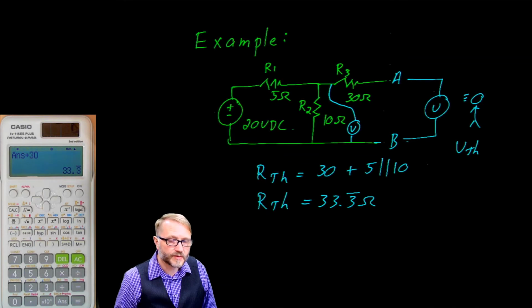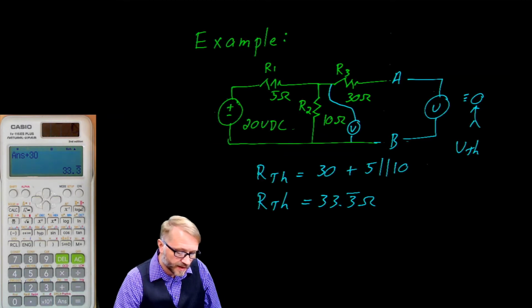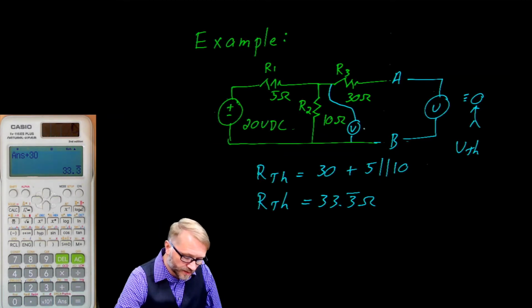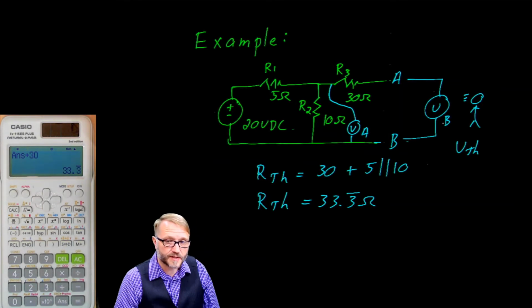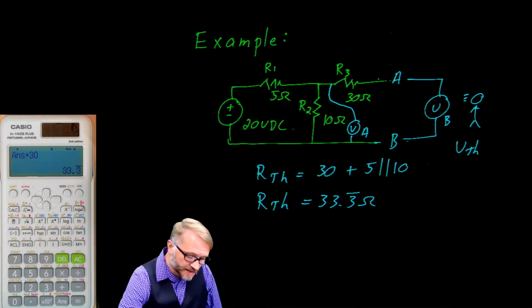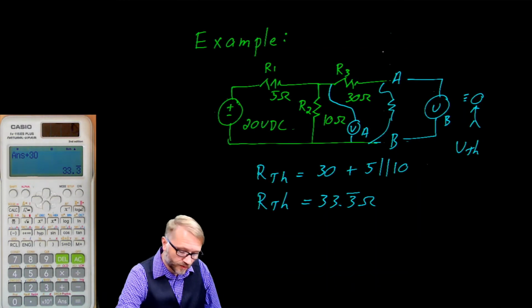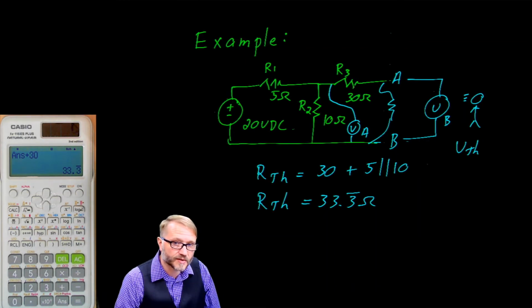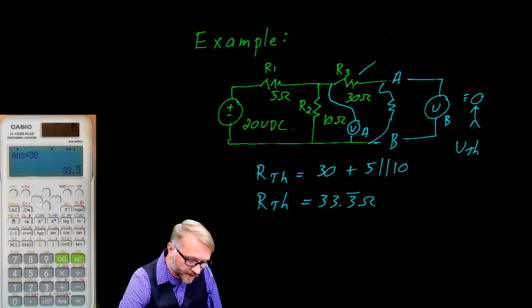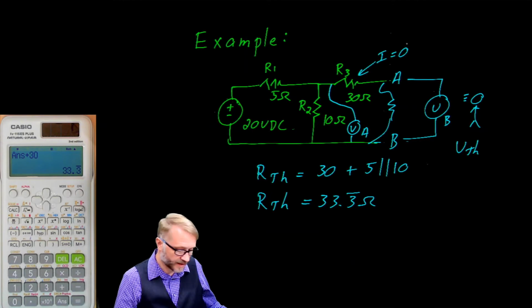Would you agree that for this circuit, and this circuit only, these two voltmeters, we'll call them A and B, will indeed read the same voltage? And the answer is yes, because there's no load out here, right? There's no load. Therefore, there's going to be no voltage drop across R3 because the current right here is essentially 0. Okay, so keep that in mind.